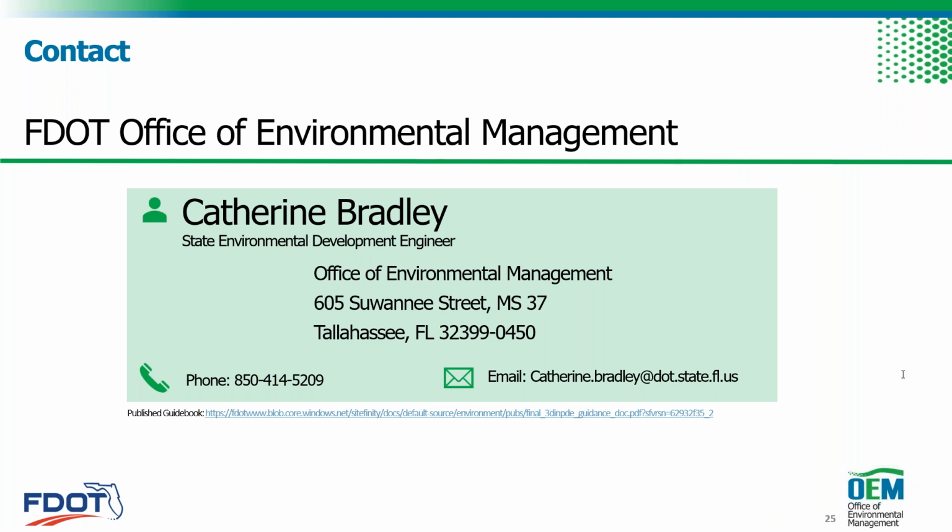Eric, you're smiling. Maybe you do have an answer for the QC process. Yeah, I was reading that one at the end. So my thoughts would be, when we're at that stage, let's say you are at your preferred analysis, your preferred typical section, right? And now you are beginning to develop the horizontal curve and maybe the vertical curve. The same processes that would apply to the roadway design could apply there as well, right? So if there's a checklist that your roadway production group utilizes that checks it against the design speed, I'd say utilize those same elements there.